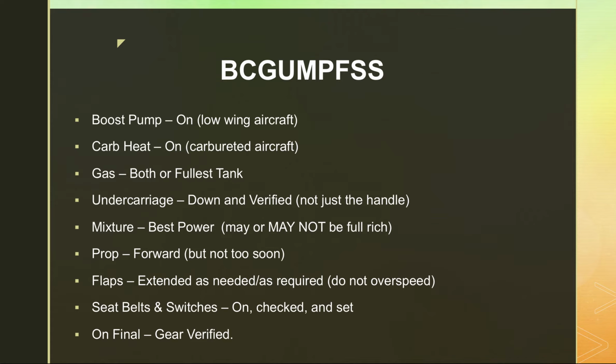Once you start flying complex aircraft, you're going to be doing it a whole lot, like 3 times in each landing. So BC GUMPS, I've added obviously quite a few letters onto this one because of my couple years of instruction doing this. Depending on your aircraft, if you're flying a low-wing aircraft like a Piper, you need the boost pump on for takeoff and for landing. If you're flying a high-wing aircraft, most POHs don't require that.